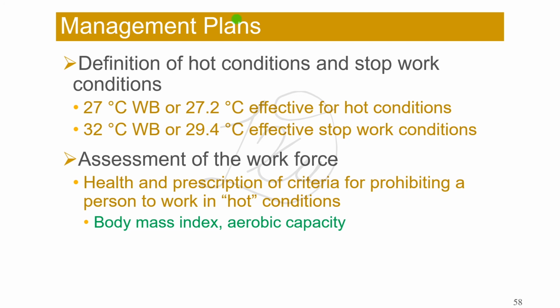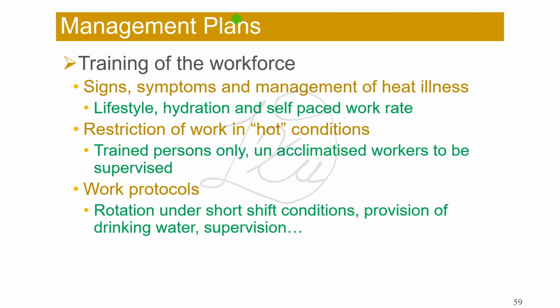Workers should be assessed based on their health, and criteria should be prescribed for prohibiting a person from working in hot conditions. Lastly, a workforce that is required to work in hot environments should be trained to recognize the initial symptoms of heat strain and to adopt sensible work habits.